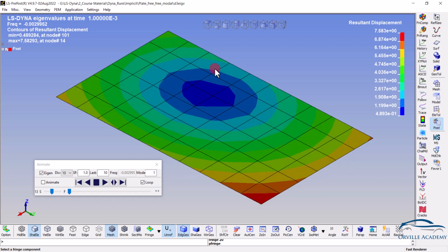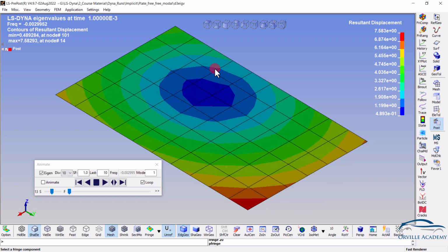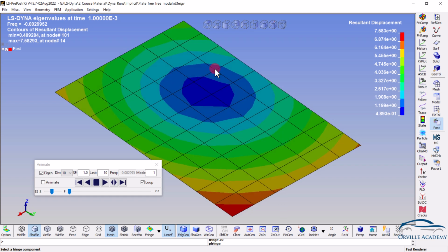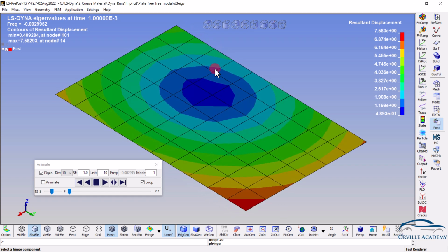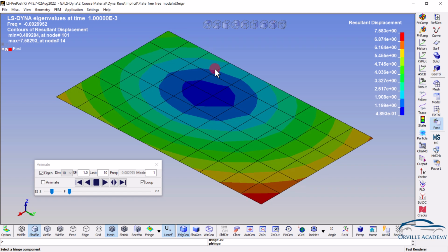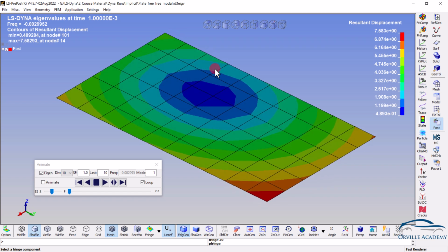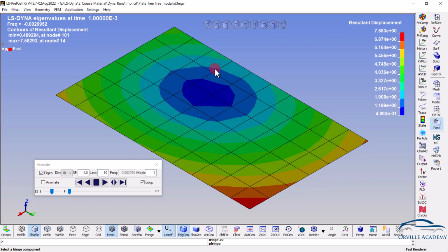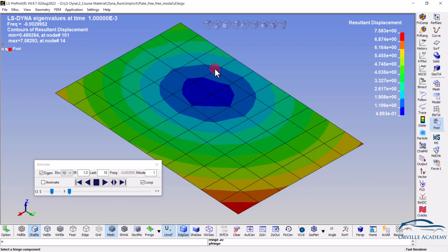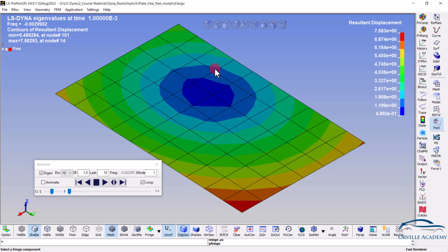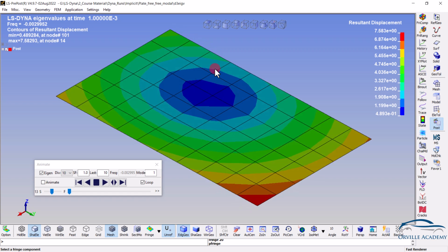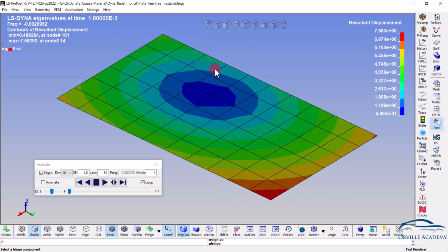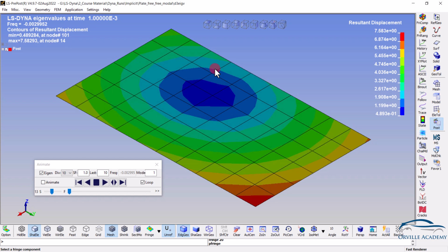Now corresponding to those degrees of freedom, there is going to be frequency which will be null since we don't have any boundary condition. Now what essentially a boundary condition does is that it will restrict the motion in that direction. Since we don't have any boundary condition, that means this object can move along that direction very easily. Since there is no restriction, automatically the frequency is going to be 0 only.